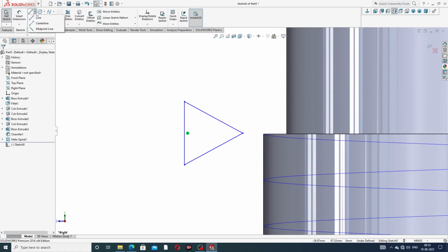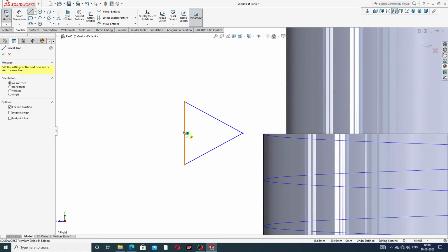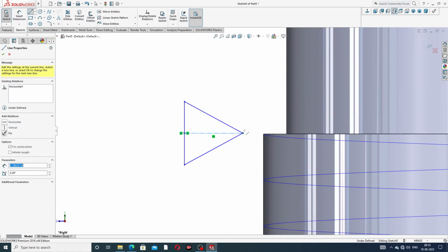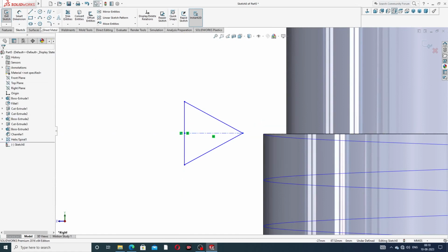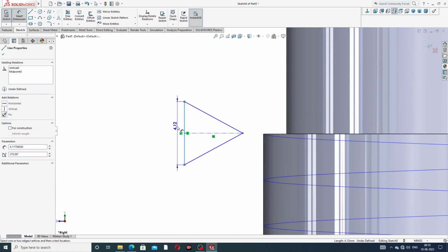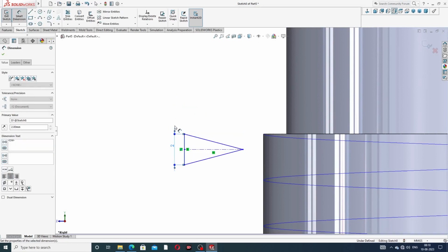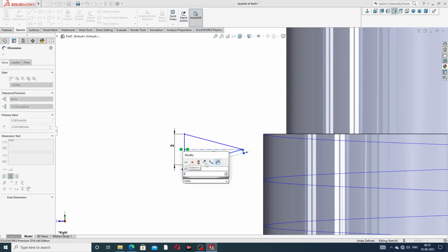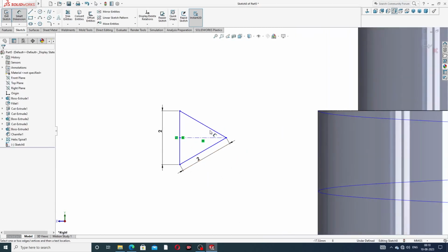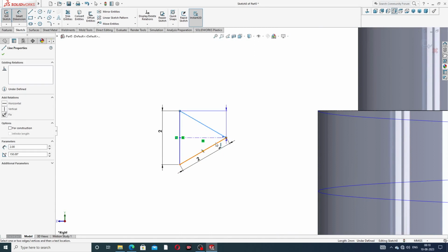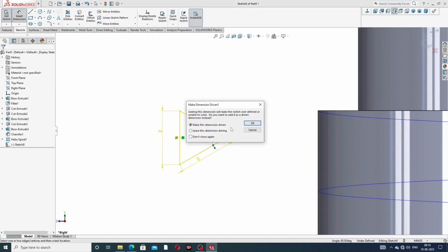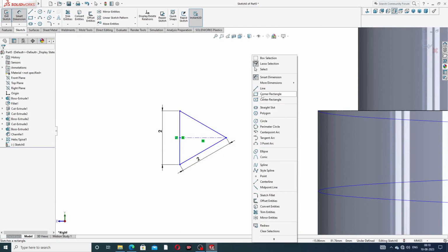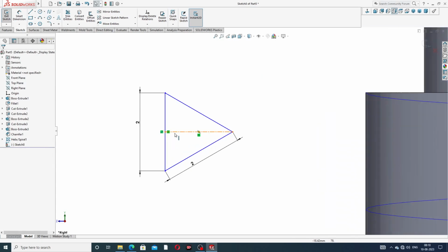And also select a center line, drawing this to this, and okay, this length is 2 mm, and also this length is 2 mm. Okay, and this angle is a 60 degree angle. Okay, not defined. All is perfect. Okay, this length is horizontal, then all is looking perfect.